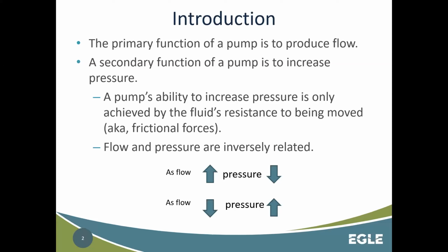All right. So again, we're dealing with an incompressible fluid, and we're going to talk right off the bat about pumps, right? The pumping systems, and the primary function of a pump, as we know, is to produce flow. Get that water moving, right? And the secondary function of that interaction with the flow of water is the increase of pressure, right? We have an increase in pressure moving that flow of water through that network of pipe and the friction that we build up.